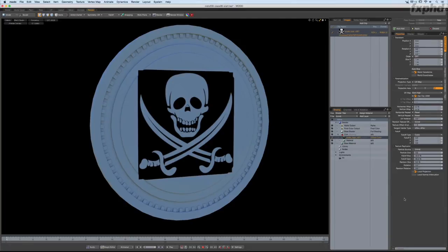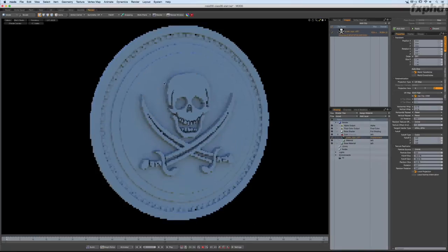So now that we have our pirate texture in there, and we're starting to build the illusion that we're after, let's go ahead and get this integrated into the scene itself. Now, clearly we don't want to use this texture as part of the diffuse color network. So I'm going to change the effect from diffuse color to displacement because I want to create a little bump out. And once my computer updates here momentarily, we shall start to see the effect, and there we go.